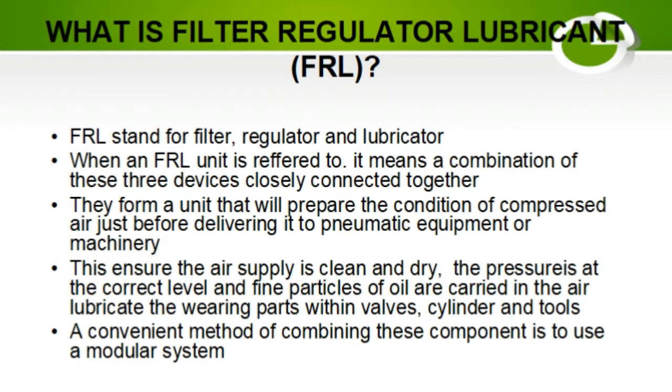Standard for filter, regulator, and lubricator. When an FRL unit is referred to, it means a combination of these three devices closely connected together. They form a unit that will prepare the condition of compressed air just before delivering it to pneumatic equipment or machinery. This ensures the air supply is clean and dry, the pressure is at the correct level, and fine particles of oil carried in the air lubricate the wearing parts within valves, cylinders, and tools.